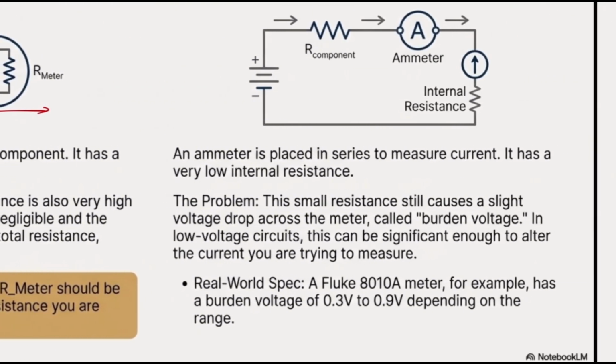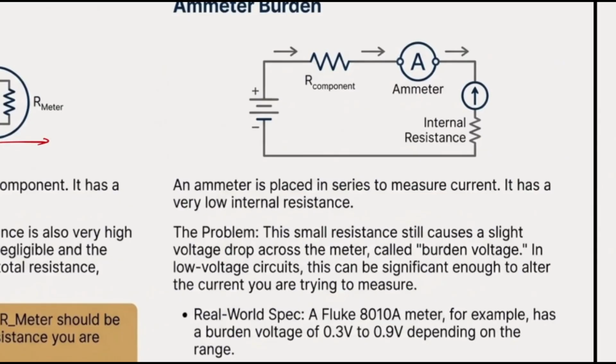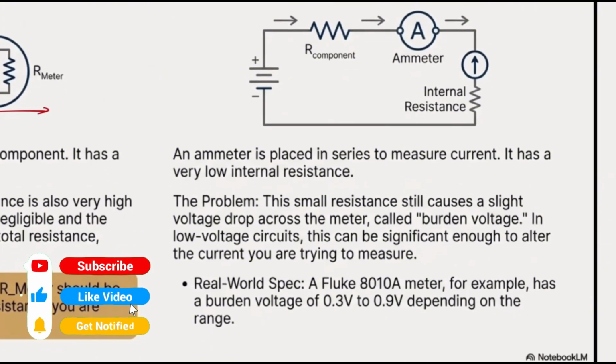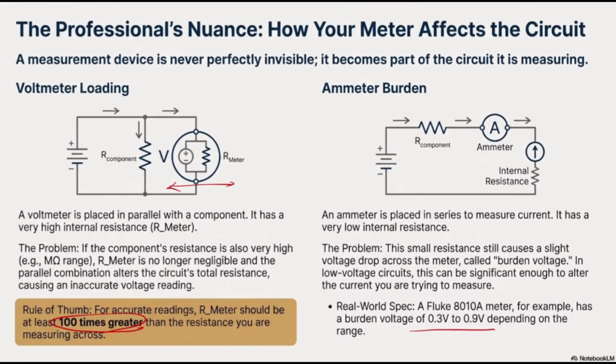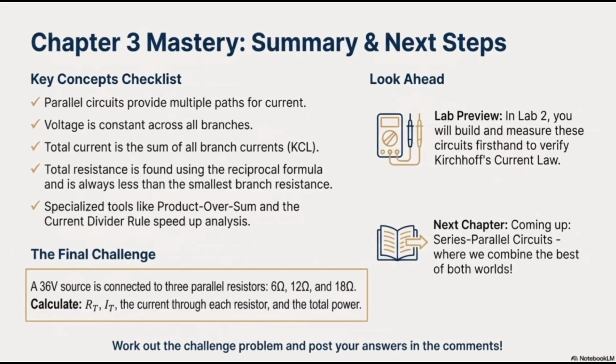On the other hand, the ammeter has a very low amount of resistance inside itself. So most of the time it doesn't have any effect, but at a point where you have a small amount of voltage, it's going to affect the whole system. So most of the time when we use the ammeter, we are talking about 10, 12 volts, not maybe 200, 300 millivolts. So you have to account for some resistance for that part.